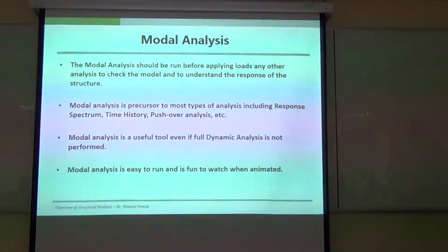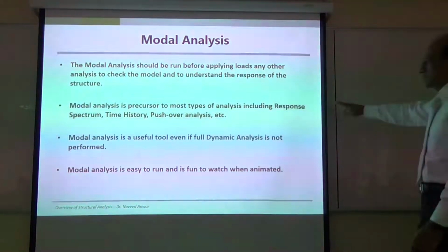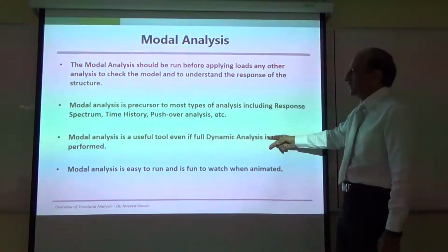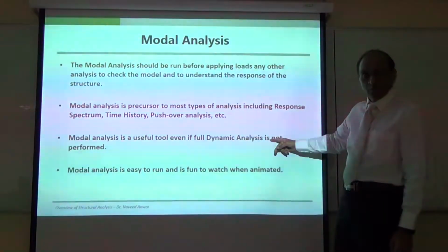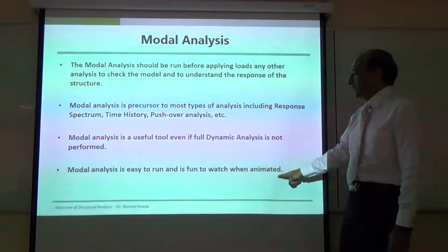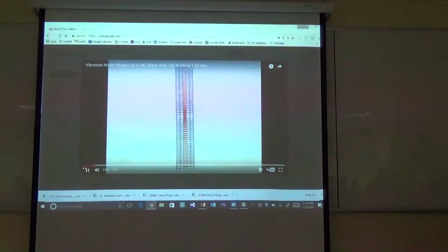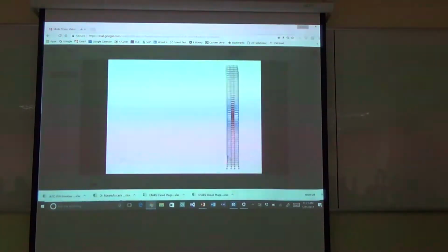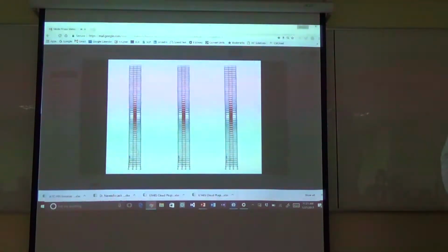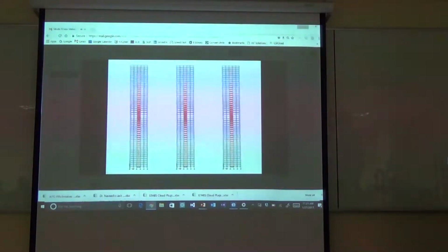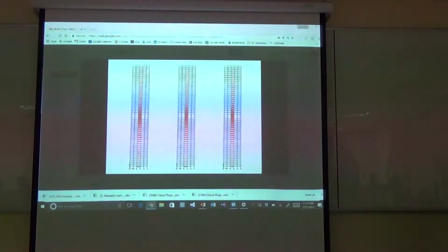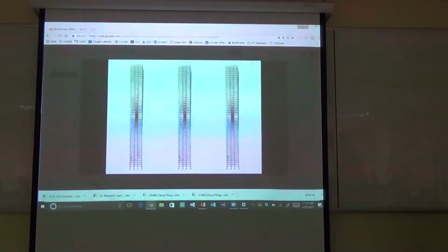We will talk more about this when we talk about tall buildings and bridges. So modal analysis is a precursor. Everything needs modal analysis. It should be run even if you don't want to do dynamics. You must run it. And modal analysis is easy to run and it is fun to watch. That is a tall building with the modal response, right? So we will talk about it later, what this response means.